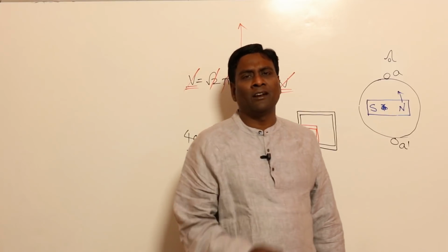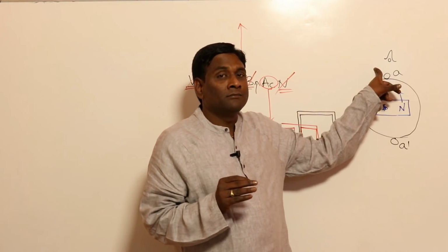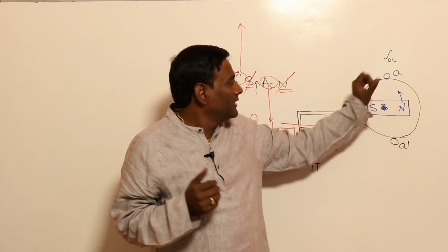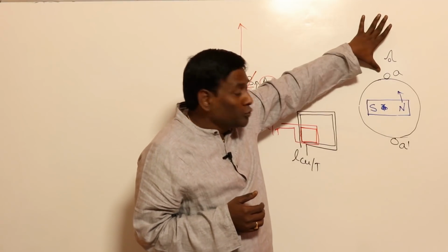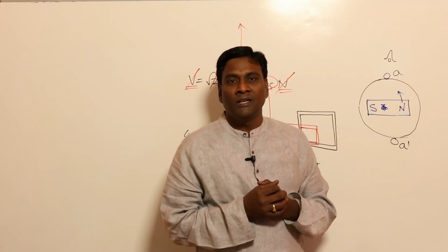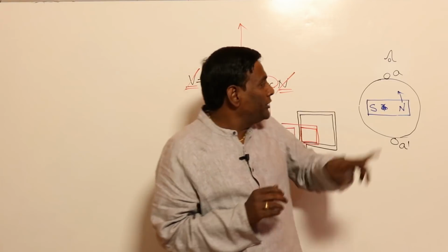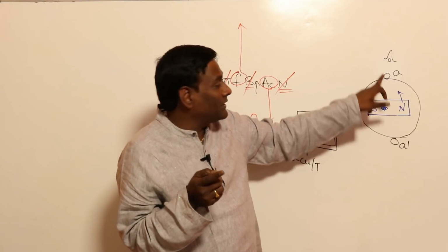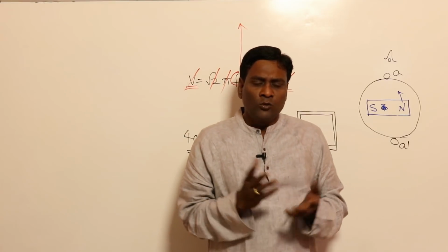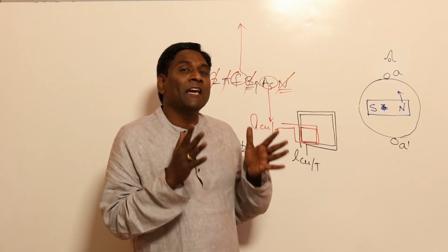It is not a signal of analog electronics here. The point to be noted is very simple: power, bulk of power, crores of rupees, gigawatts of power, giga units of energy. In order to produce induced voltage, my rotor has to be rotated mechanically. If I rotate the rotor one revolution, the induced voltage will be one cycle. So in order to get 50 Hz, 50 cycles per second, I have to rotate 50 revolutions per second. My rotor has to be rotated 50 times mechanically within that one second.